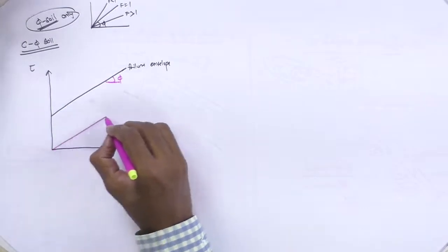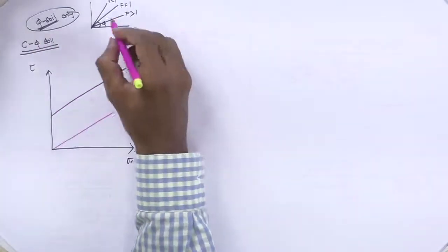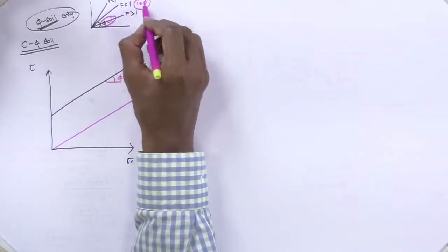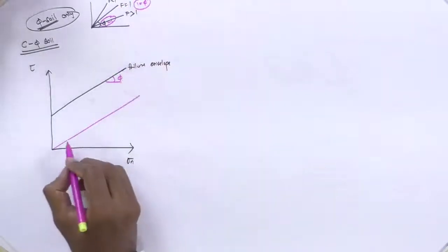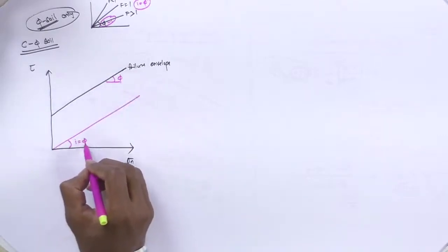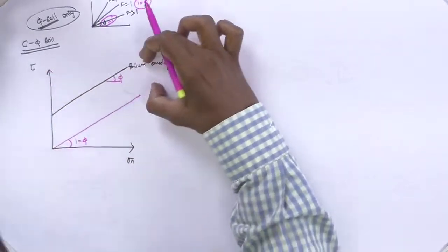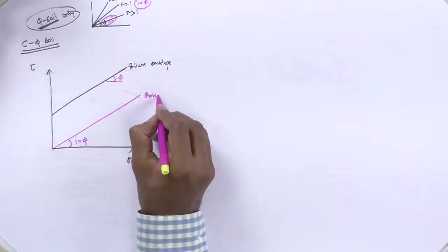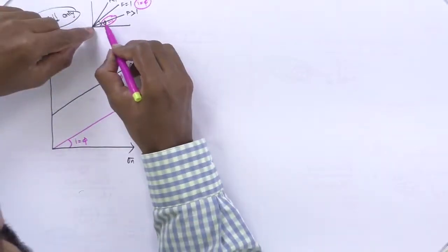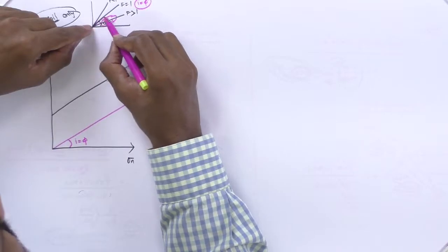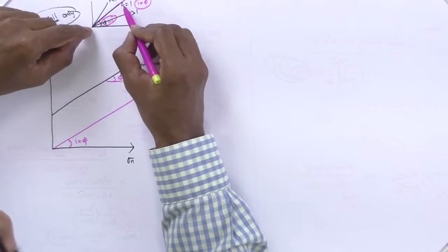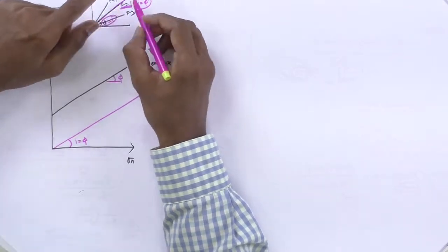Let us consider a slope like this. In the previous case, when i equals phi, it is about to fail. It is a critical slope as I have explained. So here this is the slope inclination, and this is the failure envelope. When i equals phi, this is exactly parallel with the failure envelope, whereas when i equals phi the failure line is merging with the failure envelope. So the slope inclination angle merges with the failure envelope. That is why I told you this is about to fail.